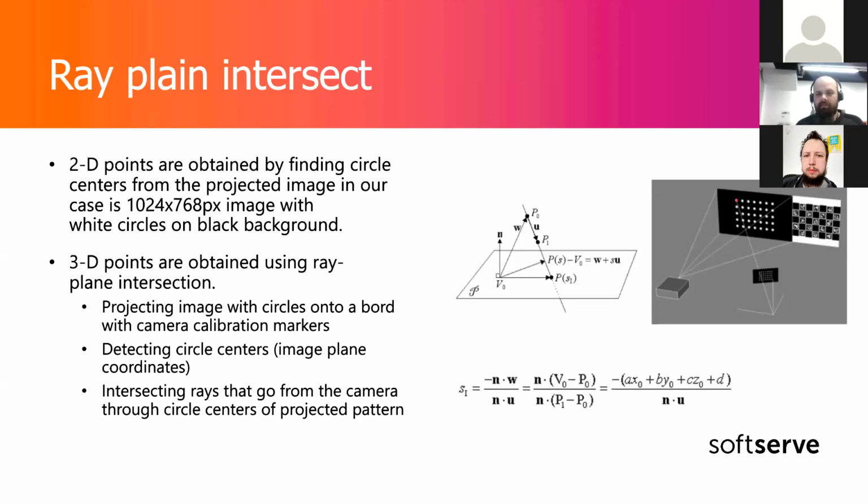And it is quite robust to light conditions, actually. So even a quite lit room can be used for the calibration. And as for camera calibration, because we are using the Charuco board, we can even have partial visibility of the board and still calibrate the camera because of the robustness of the method itself.